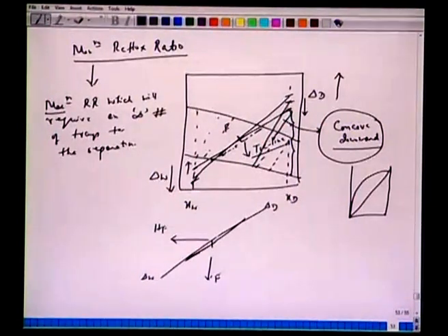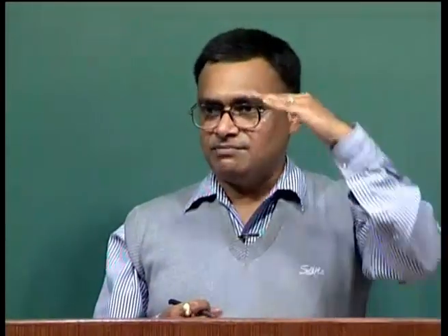So, we would like to conclude today's sections with this reflux ratios, maximum and minimum reflux ratios. All right. So, we said that if we increase the reflux ratio, then QB, load on boiler, and load on condenser increase. We have a large amount of liquid, large amount of vapor to make up for this. So, the pump requirement also increases.